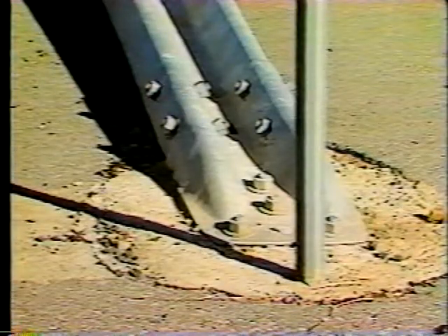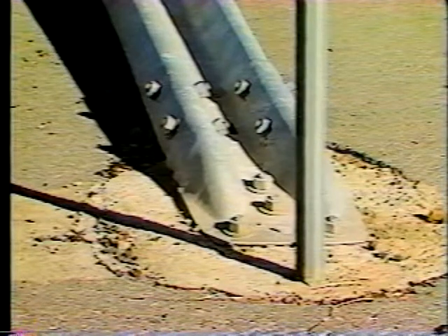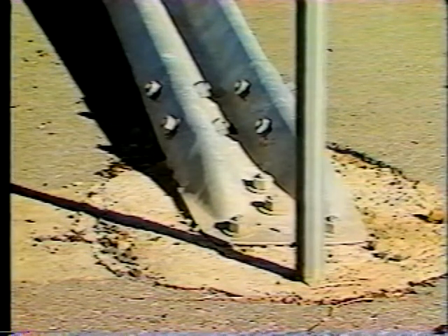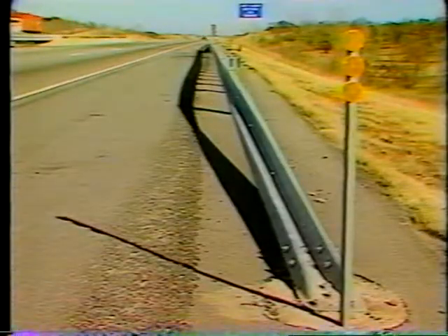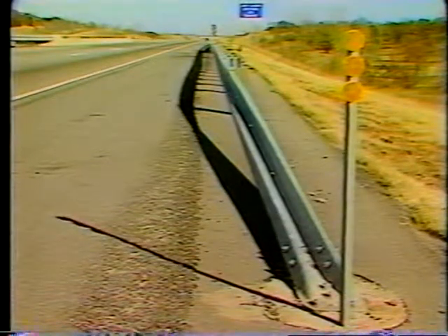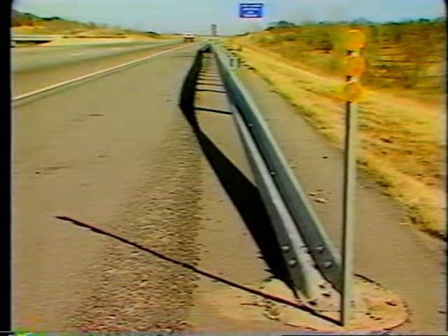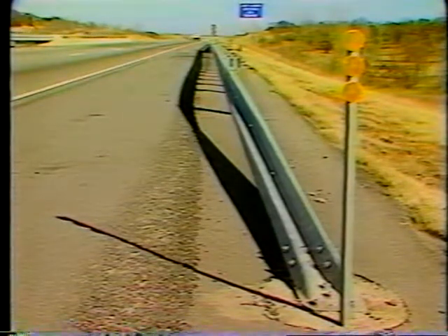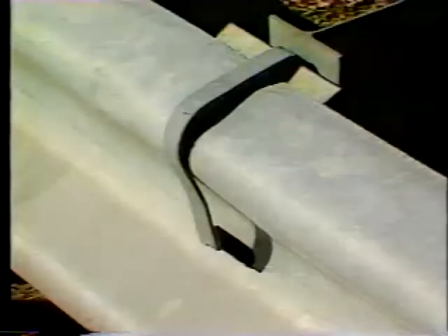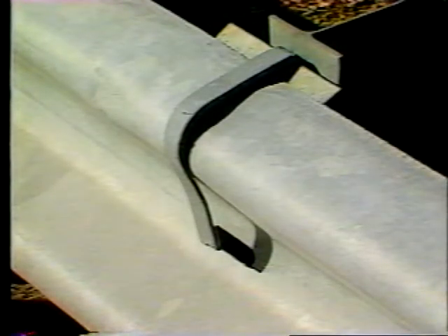The turned down end of the system should be anchored by 4 bolts to a concrete footing that's either at or below grade level. As mentioned earlier, the rail is intended to release from the first post and lie down. To bring the required quick release, several systems have been developed that work like these galvanized steel clips.